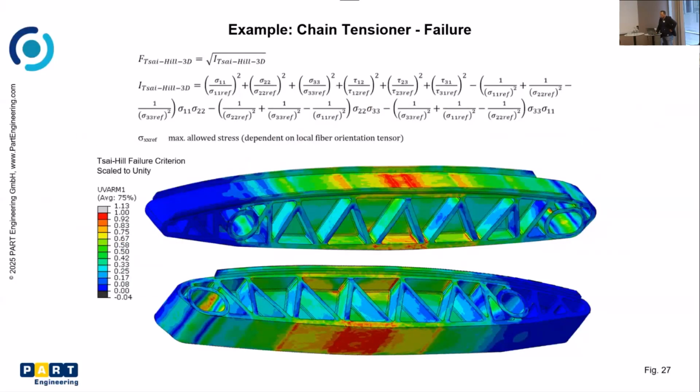Since this is the OpenRadioss Day, with quite a scientific background, I need to at least put one equation on the slides. What you can see here is the so-called Tsai-Hill failure criteria. This can be used for the post-processing to consider the anisotropy in your failure model, because, of course, such things as equivalent strain, Mises, or Max principal do not apply anymore when it comes down to anisotropic material behavior.